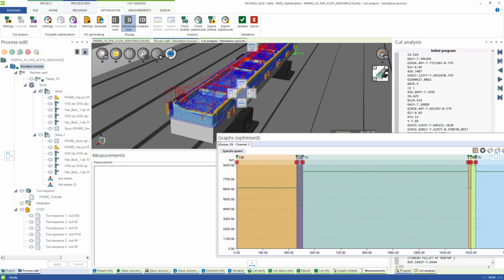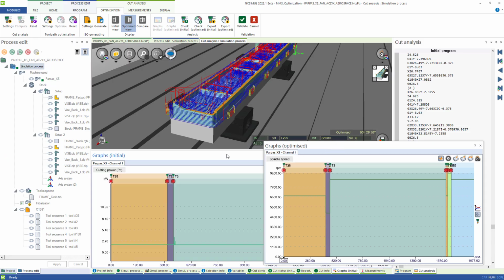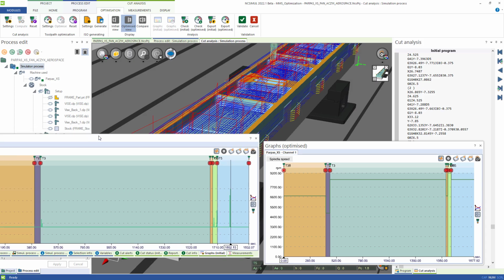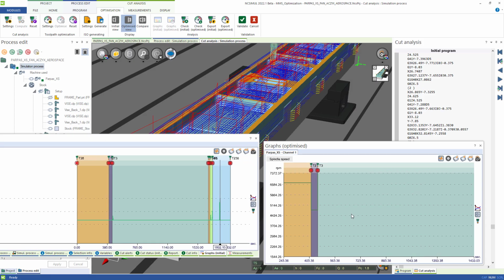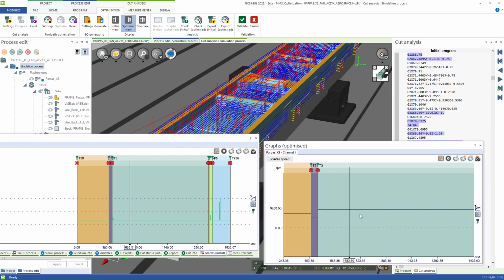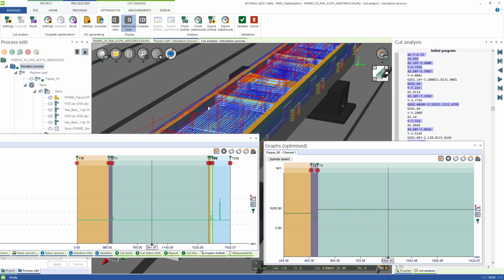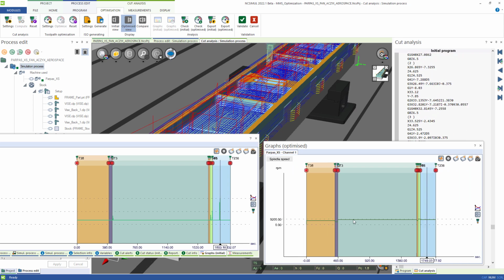And then if you want, you can kind of grab them and dock them to wherever you'd like inside the 3D window here if I wanted to see exactly what the difference was when they were side by side. You could do all of that. And they move simultaneously. So again, if you see at the top, you can see the machine moving, the G-code moving, and where you're at inside the simulation or the graphing tab.